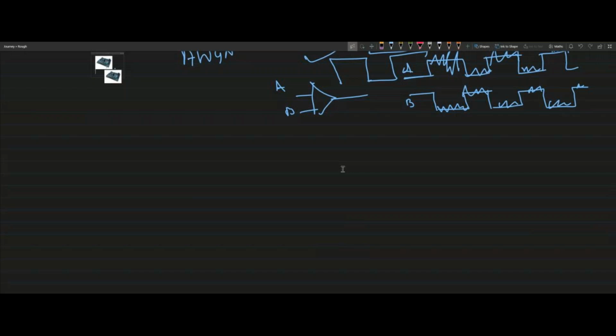What do you mean by synchronous FIFO and asynchronous FIFO? Why do we need that? Have you heard about them? The same clock will be used in a synchronous FIFO, so writing and reading use the same clock. In an asynchronous FIFO, the read clock and write clock will not be the same; they will be different.